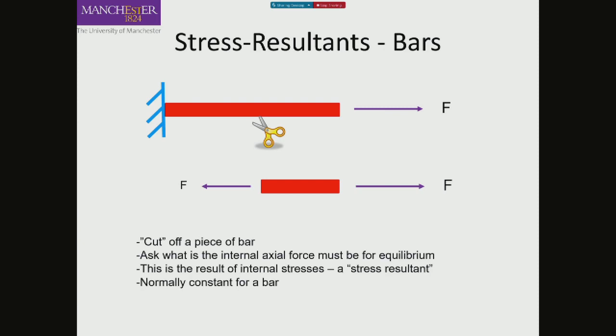If you remember, we calculated the member forces in trusses by making a cut, and then used Newton's third law of motion, saying that if it is in equilibrium, then there must be forces from the other side keeping it in equilibrium. And then we found indirectly what would have been the force inside the member. Exactly the same type of approach we will be doing now. You will cut a piece of a beam and see what sort of force will keep it in equilibrium.